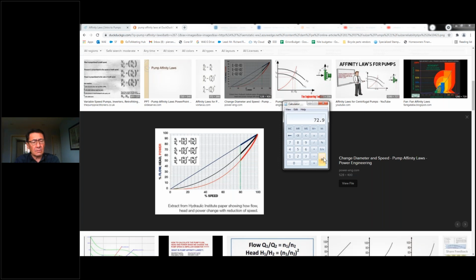It doesn't control speed. So with your no VFD pump application, you're always running at full speed, therefore you have no ability to drop the power. What you can do in order to vary your flows, you can put a bypass valve out there or a throttling valve, various ways to vary the flow on the output, but you can't vary the speed of the pump itself.